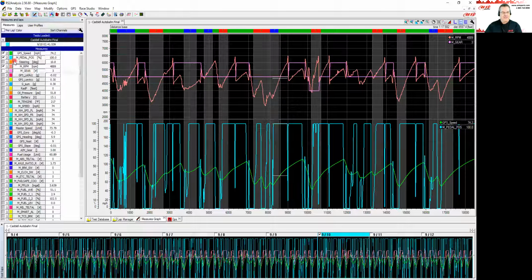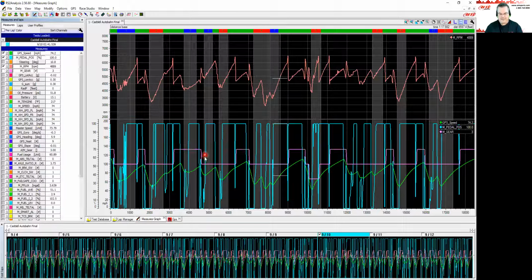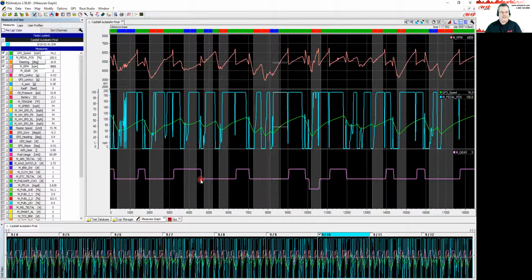And the way that you change these or recognize that is over here on the left edge. When we went into the mixed view, one of the changes you saw was these numbers showed up. And these numbers are signifying where in the windows you're looking at it. So if gear position is right here in number 1 right now, if I click on that one time and turn that to a 2, gear position now is here at the bottom in the 2nd window. Okay, I could put it into a 3rd window if I wanted to, just by clicking again.